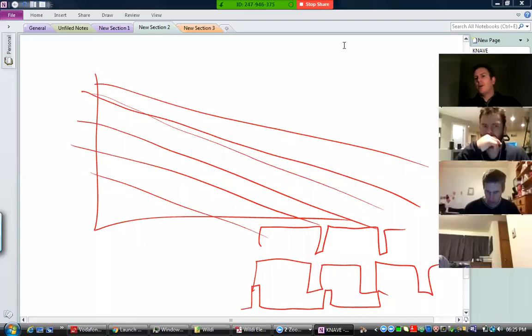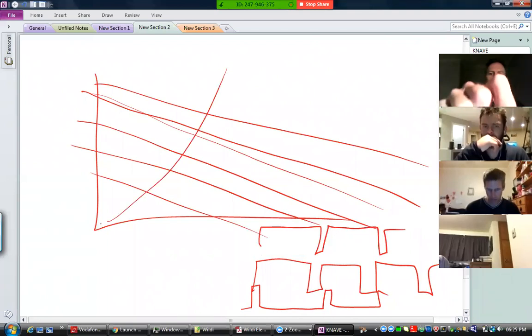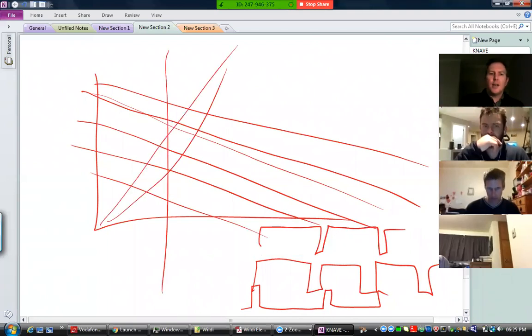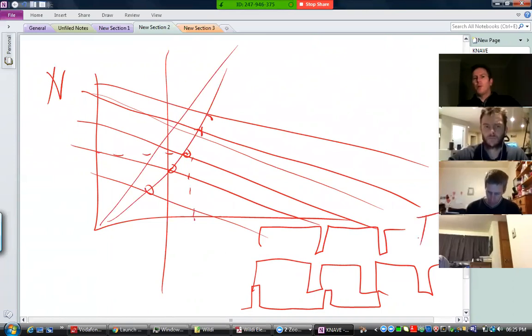So for each reduced voltage, you'll just get a graph like that. Then your load curve, regardless if it was an exponential or a linear or even something more constant, every time it'll just intersect at a different place. Each of those intersection points gives you a specific torque and a specific speed. So that's the more common way of doing it.